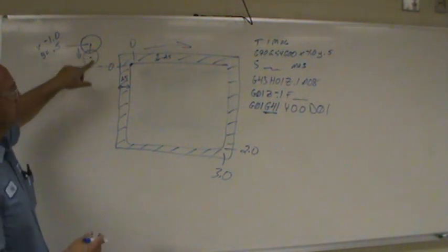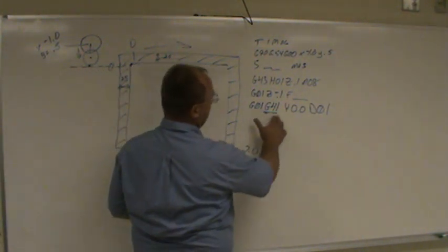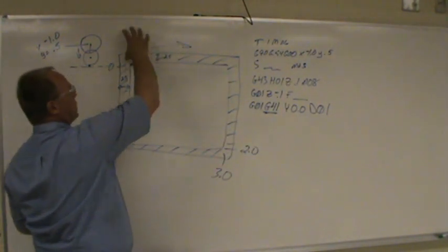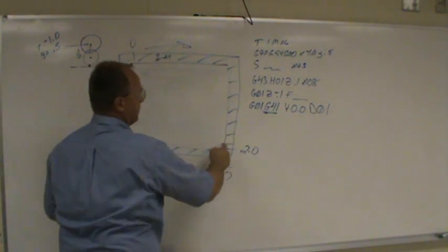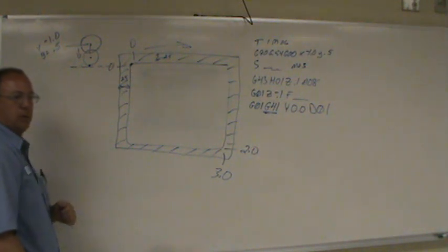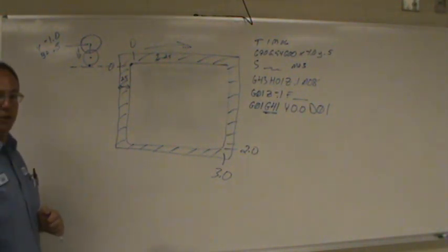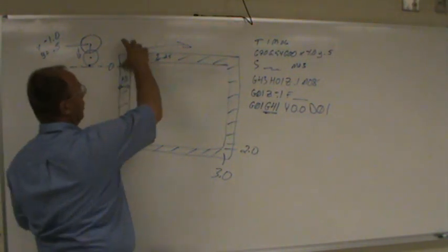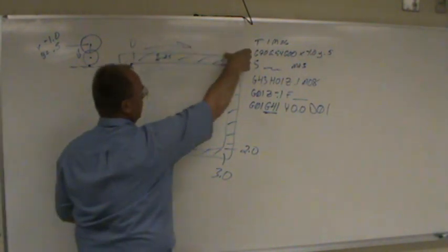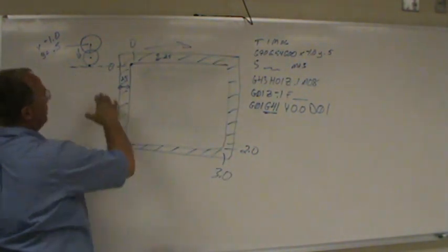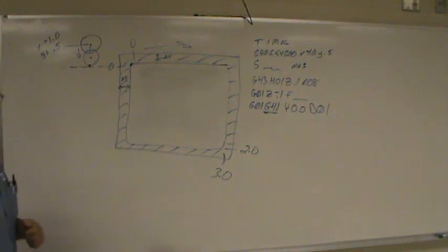So this is the beauty, I guess, of using cutter comp, because it knows how far it has to stay away from the outline of your part by using the G41. You don't have to sit there and figure out half of my cutter, and I have to go halfway this way and past that way. The machine will figure all that out for you.